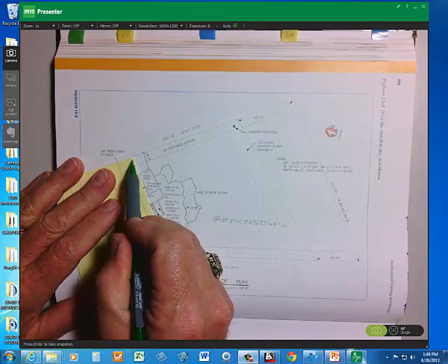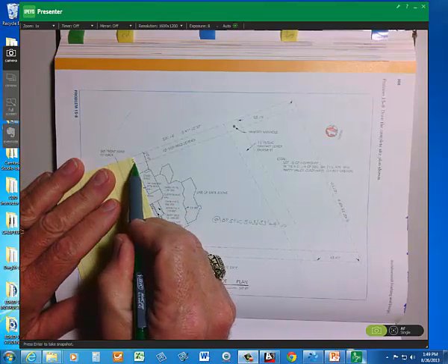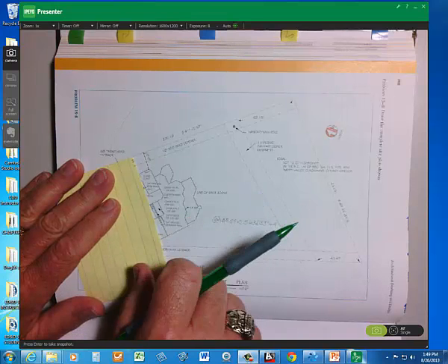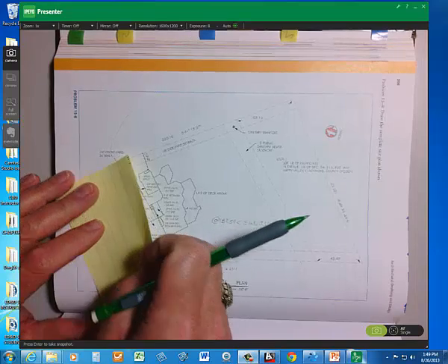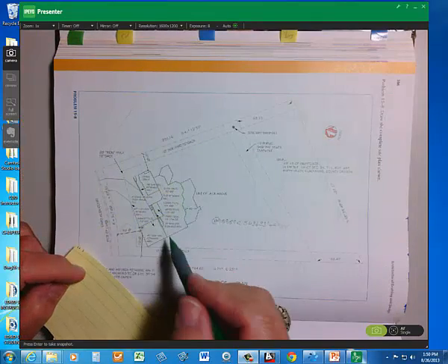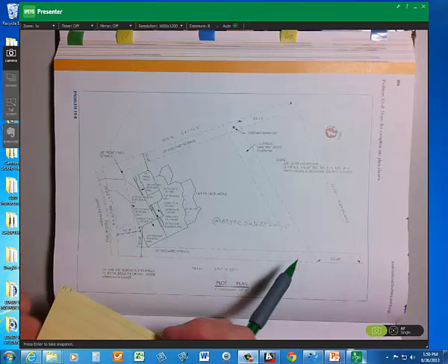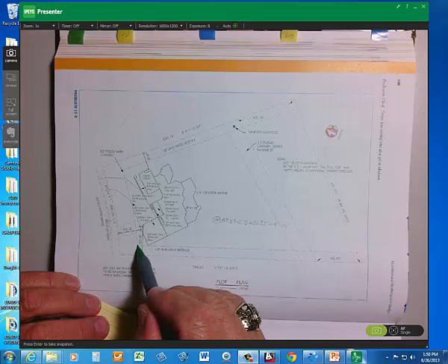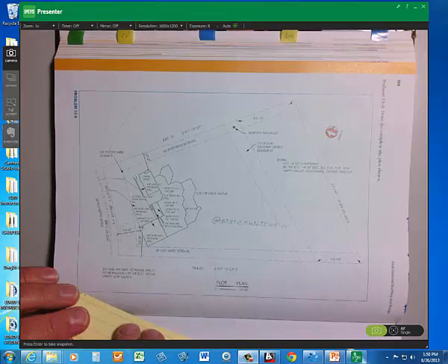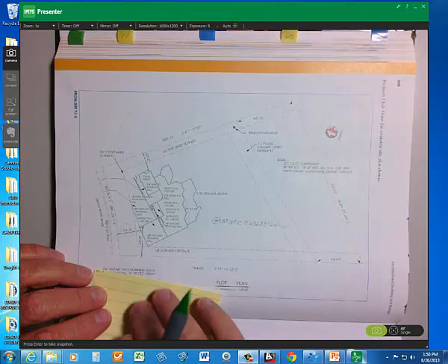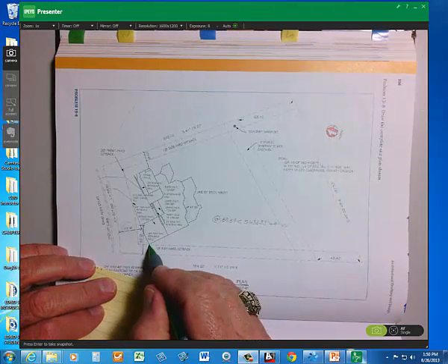Divide up the 10 foot, so that would become 5 feet, and then divide it again, that's 2.5 feet. Then you can use that to measure the building to lay it out in CAD. To find out where to start it, you would measure from this corner after you got the property laid out. Then you'll use this paper scale and find out where this corner is.